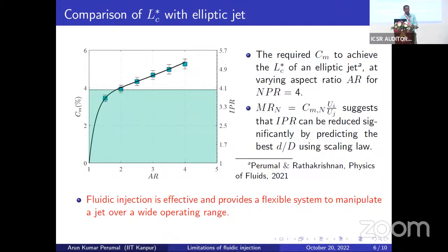Okay, and my last thing was more of a comment. May take it or leave it. So you made a comment that you can turn this jet on and off, unlike a chevron, which is passive and creates a parasitic drag. Yeah, but still there are variable chevrons also. But what I would also argue is when you have this, you are carrying all the infrastructure with you. Exactly. So you are still creating a parasitic drag, even though you turn the jet on and off, and you are still not out of the woods on that.